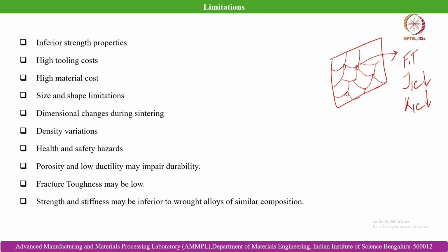Of course, if you are going to manufacture a complex contoured object by the powder metallurgy route, as I told you, you can effectively manufacture it in net shape, but that often deals with a specially contoured mold. So, the mold cavity machining makes the tooling cost much higher.